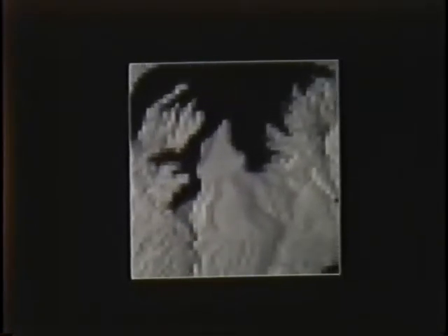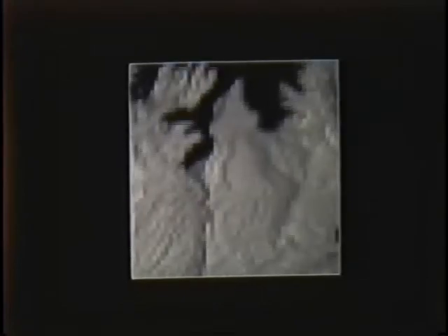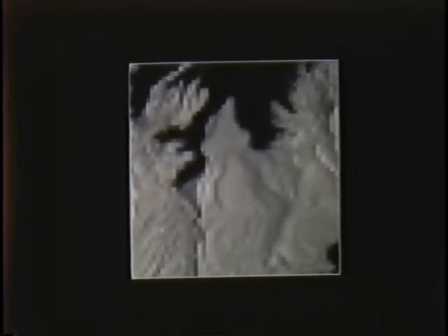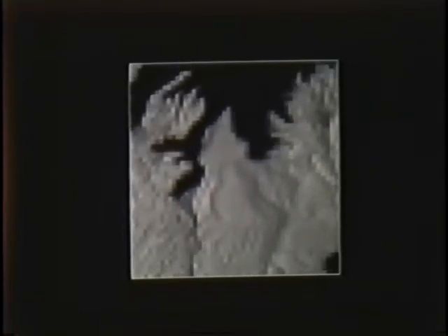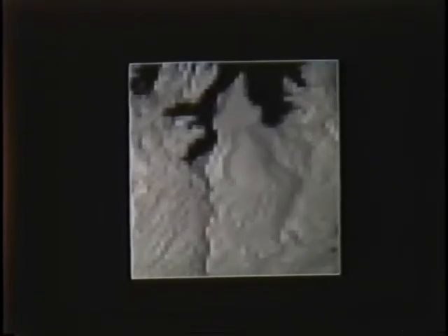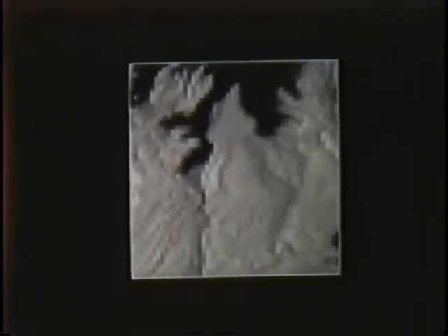Jitter and drift are also functions of the time between frames. An airplane, which we think of as exhibiting a lot of vibrations, can produce fairly stable frames if the frames are taken very rapidly, such as 100 frames per second. On the other hand, a satellite, which we think of as being very stable, might produce frames with significant drift if the time between frames is long, say 10 seconds. As we will see later, large shifts, usually exceeding 1/2 a pixel, can be very destructive to the signal coming from a target.